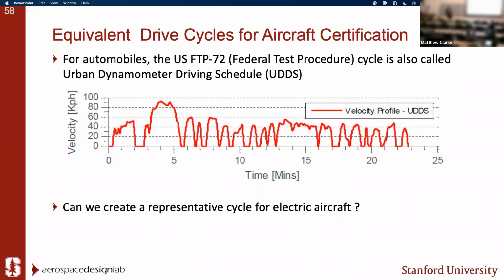So going back to the aeroacoustic noise work, the optimization problem, I have two questions related to that. One is, what role does prop phasing play? For example, the eVTOL concept that you showed has about 10 props. Thinking in terms of harmonic noise production, specifically in the radial directions, can you potentially redistribute or get active control? You know what I mean?